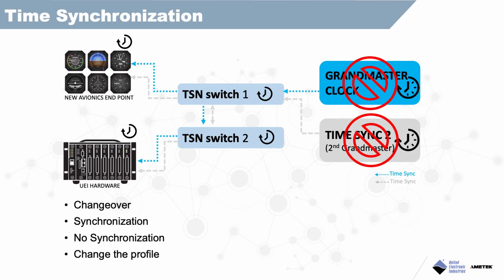If we just look at time synchronization or the AS protocol, how does it handle the changeover, the loss of the grandmaster? As a grandmaster, we have complete control. We can change all aspects of time. No time, get them both out of there. Time jumps or shifts, change the synchronization or make it not synchronized. Change the profile for PTP. For everything to work, everyone needs to use the same profile. So what happens when they're different? Change the frequency. All this can be tested to ensure your device will be able to be synchronized using these grandmasters and using the AS protocol.